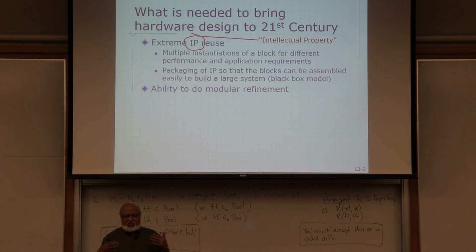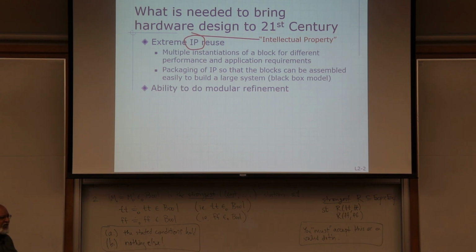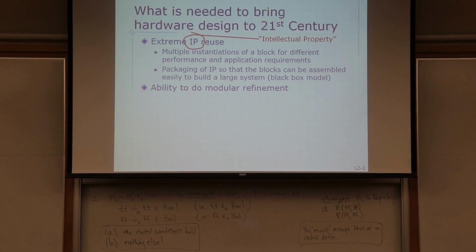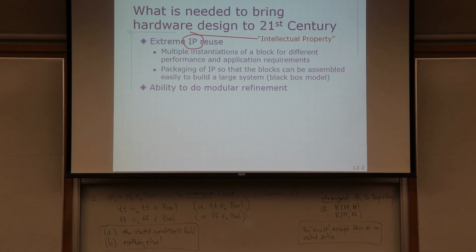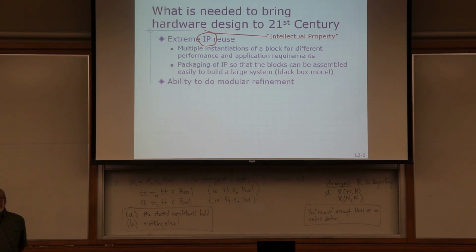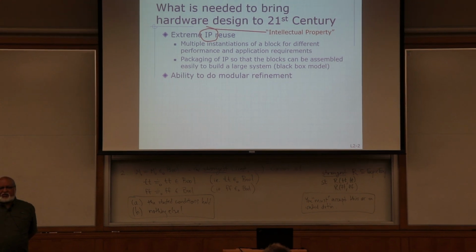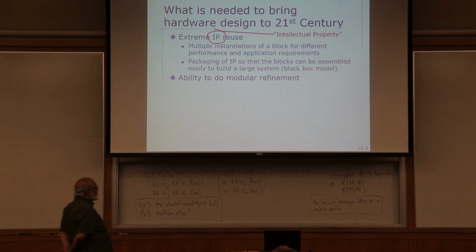So you need some way of saying that I can take some module, refine it, plug in another one, without breaking the whole design. And we want pretty ironclad guarantees on this modular refinement. The other reason is that often these blocks are designed by different people, and we don't know how well they'll work in conjunction. So when we do performance analysis, when we do power analysis, only then we start learning, oh, this is the problem one. Maybe you should go and do something. You are the one who's consuming 85% of the power. Right? So let's focus on that block to reduce its power consumption and so on.